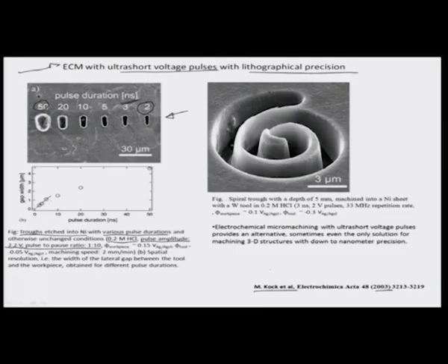Also, the potential that they are using on the workpiece is close to 0.15 volts as measured with respect to the AgCl electrode, the silver chloride electrode, and that on the tool is measured as minus 0.05 volts, again as calibrated with respect to the silver chloride electrode. Okay. So, electrochemically they have very nicely been able to establish the independent or individual potentials on both the cathode as well as the anode.